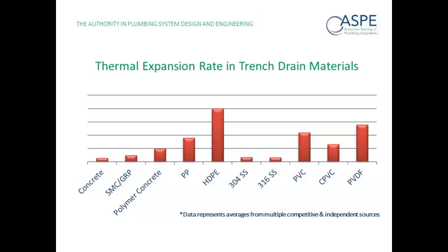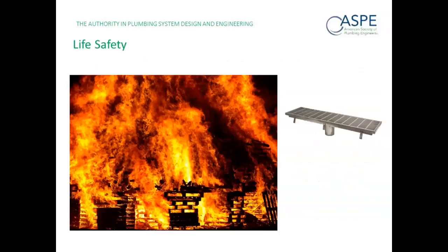Yeah, we're going to show you that crack. We've actually got a slide that displays that very clearly in about 5 or 6 slides. So we'll get there. But the point is that with a larger thermal expansion rate, you become separated between the drain and the floor, creating a gap that can then grow bacteria a lot faster. But to Scott Steinler's point, we're going to get to that in a further slide.